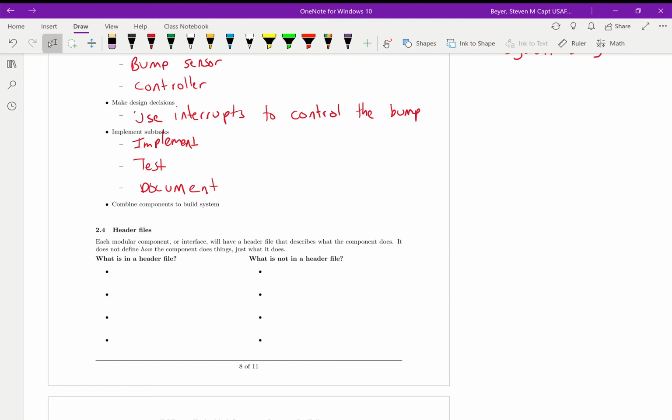All right, let's get a little bit more into C coding specifics. In C, in your starter files, you'll see this include folder. This inc folder will include .c files and .h files. A header file is what allows us to describe the component. So you might see a bump.h or, I think it's reflectance, which is the line sensors .h.